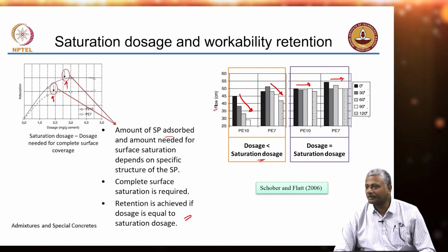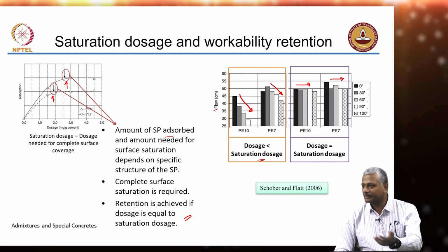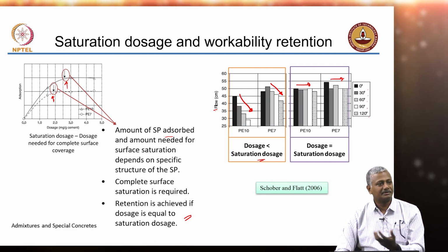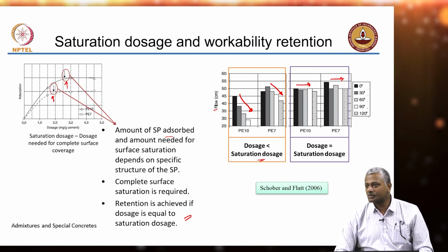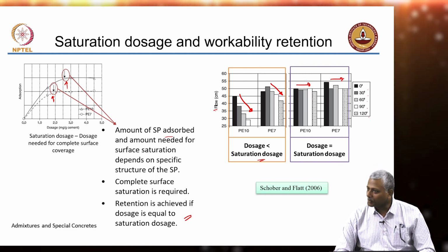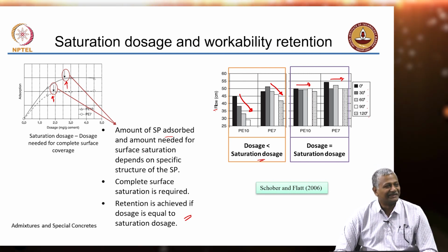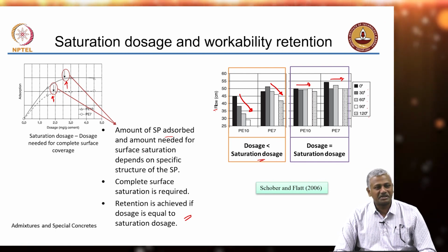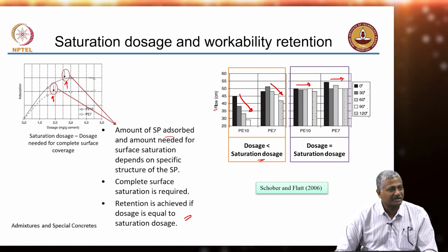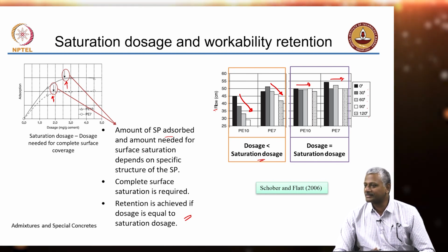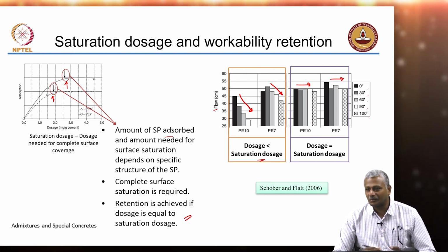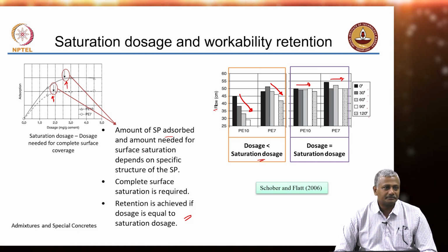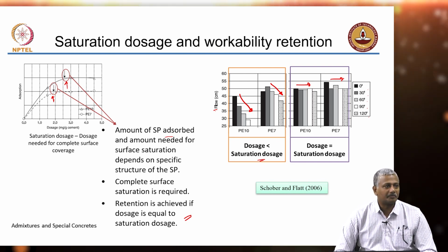You can probably try jacketing. Here the designer has to come back in again and see whether, at that strength of concrete, the column is able to take its loads. And it turns out in most cases it is able to take the load, even if it is 10 to 15 megapascal strength. We have over-designed the structure so much, it is still working, no problem. But what is the problem there? Durability is the problem, right.